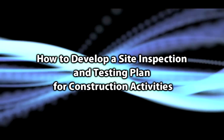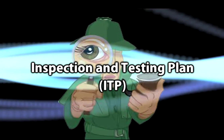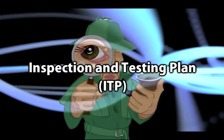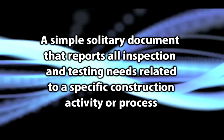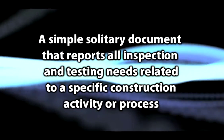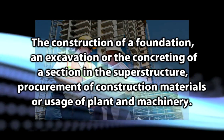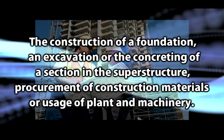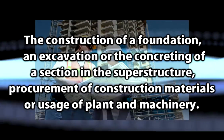How to develop a site inspection and testing plan for construction activities. The main purpose of an inspection and testing plan, or ITP, for a construction project is to have a simple solitary document that reports all inspection and testing needs related to a specific construction activity or process. For example, on a construction project, it can be the construction of a foundation and excavation, or the concreting of a section in the superstructure, procurement of construction materials, or usage of plants and machinery.